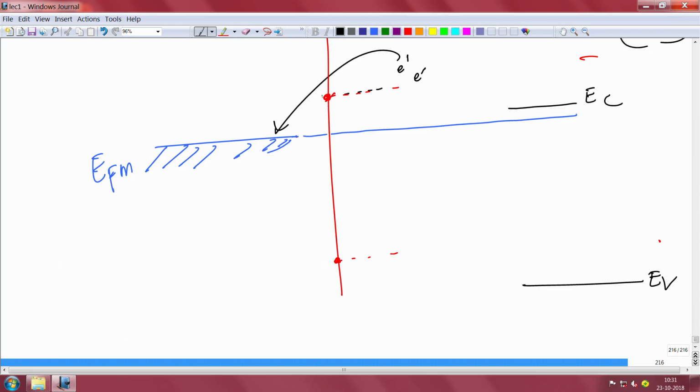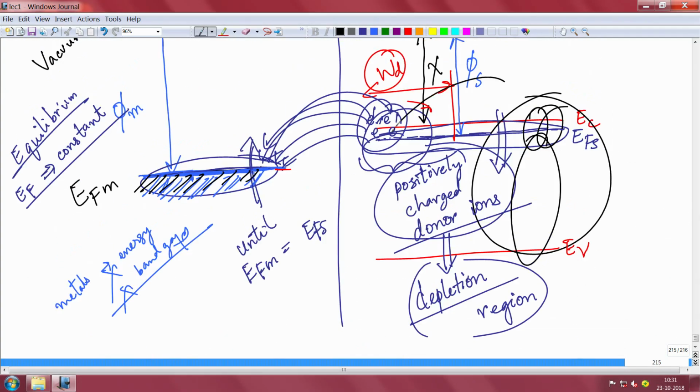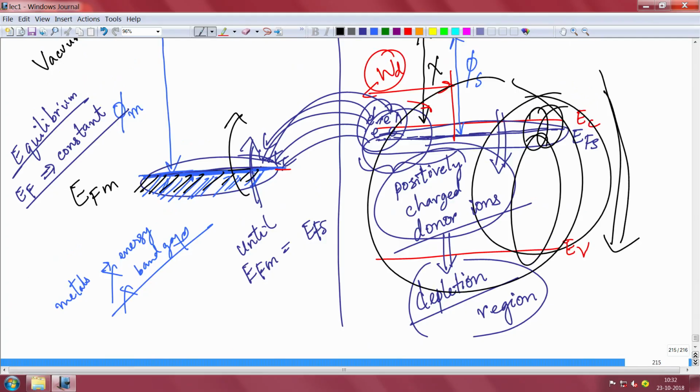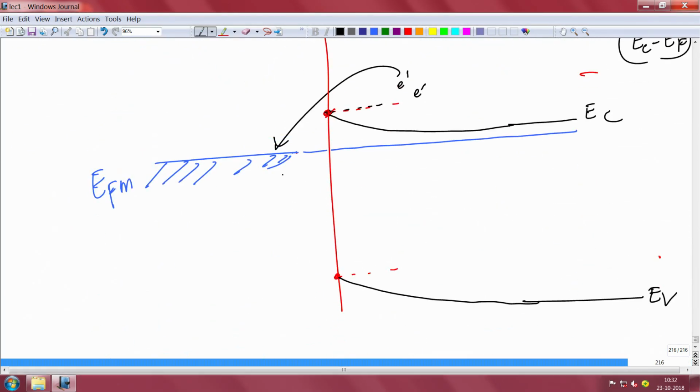Now, you remember this point is fixed from the conduction band in a position initially. So, basically the conduction band will bend up like this, it will come like that. So, you see the conduction band has bent up because essentially the whole thing is brought down, by fixing the conduction band point and the valence band point here, and then you move the whole thing down until the Fermi levels align on both sides. So, the Fermi level is aligned.